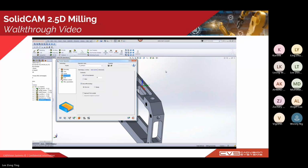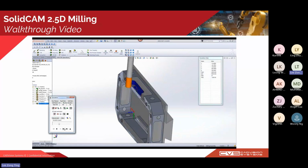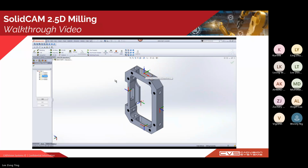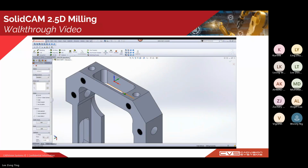After we are done setting up those parameters, how we want to cut these parts, we can simulate it again. You can see how it approaches the pocket from the outside when the pocket has an open area. Now we are going to machine another side, which is a true pocket right here.